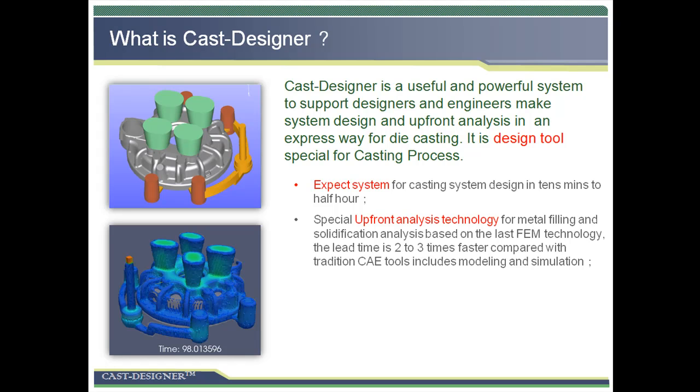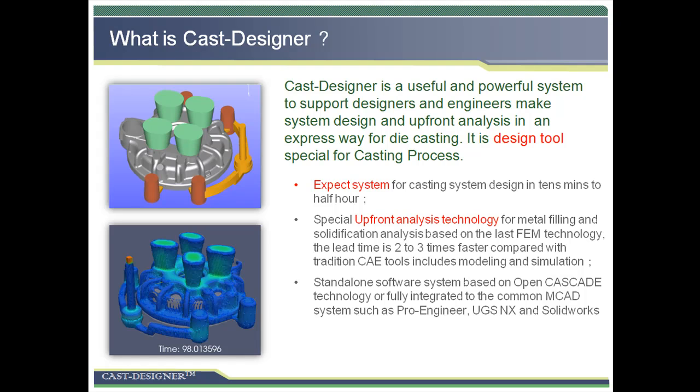Second, using the finite element method, Cast-Designer can make upfront analysis for metal filling and solidification. The lead time is only 1 hour to 2 hours for almost all cases, including modeling and simulation. There are two versions of Cast-Designer available.